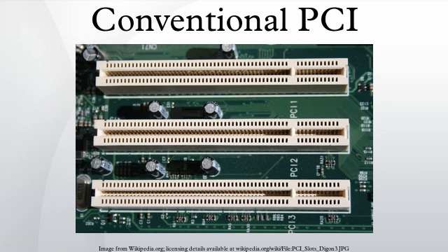0010, I/O read. This performs a read from I/O space. All 32 bits of the read address are provided, so that a device may implement less than 4 bytes worth of I/O registers. If the byte enables request data not within the address range supported by the PCI device, it must be terminated with a target abort. Multiple data cycles are permitted, using linear burst ordering. The PCI standard discourages the use of I/O space in new devices, preferring that as much as possible be done through main memory mapping.